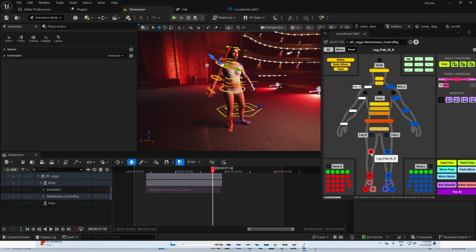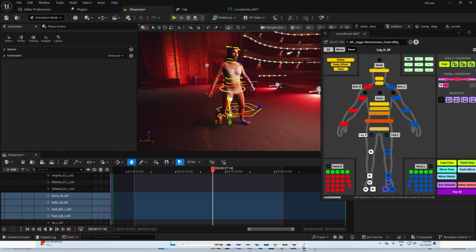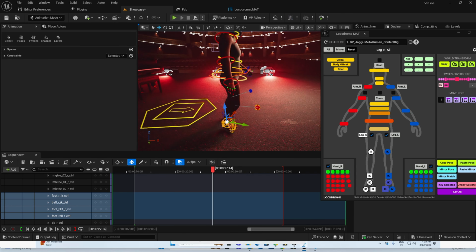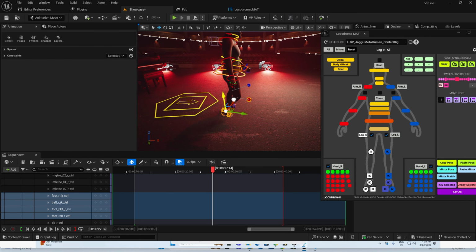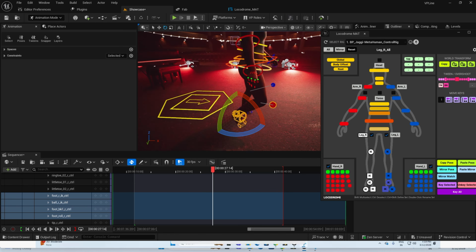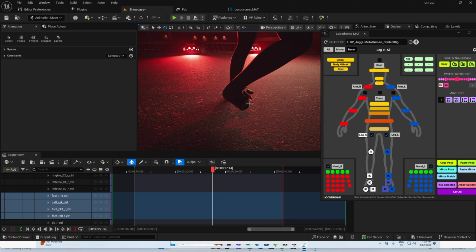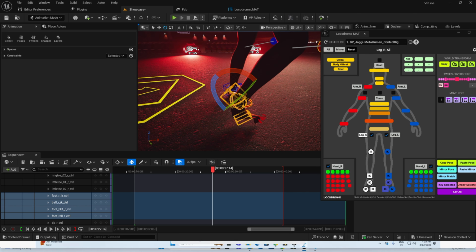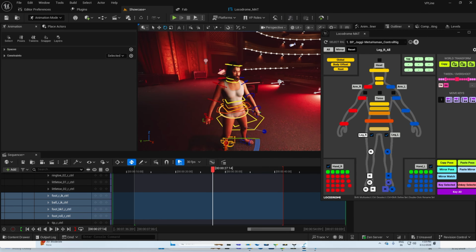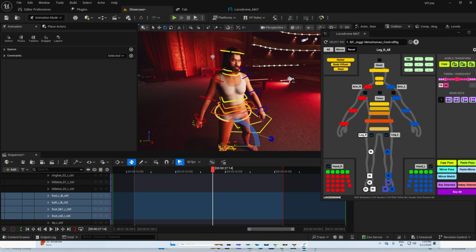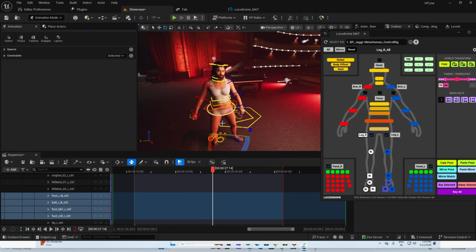And also the difference between an IK and an FK rig is something that you should look into. An inverse kinematic rig, the IK rig, if I select the entire leg and if I try to move it, it will move all the joints accordingly. If I try to rotate this, again, it will move everything accordingly. So there's no end to control rigs, and since this is just a basic cleanup tutorial, if you keep the motion capture intact, the cleanup's going to be minimal.